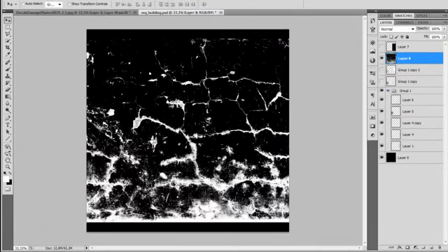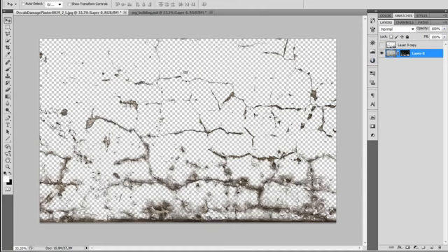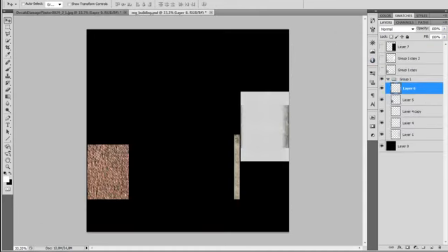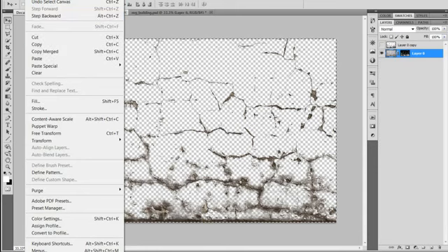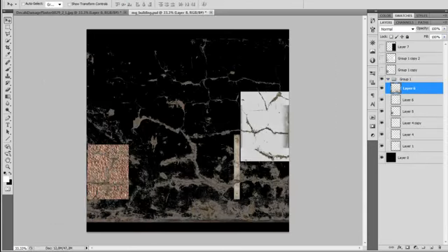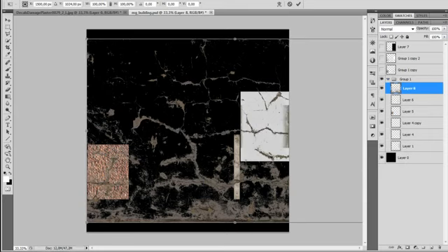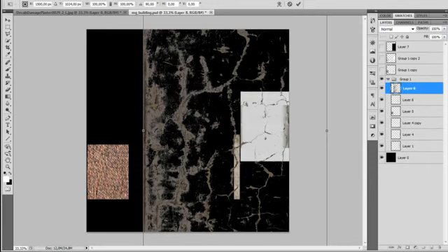I'm just going to copy the extract texture. Also, I'm copying probably the mask, yeah. So I'm just going to copy the texture. And remember to copy it merge, so that's Ctrl Shift and C, or going to edit and copy merge. So now we can orient the texture as we want it and start modifying it.